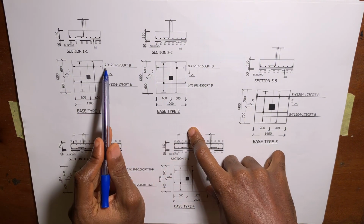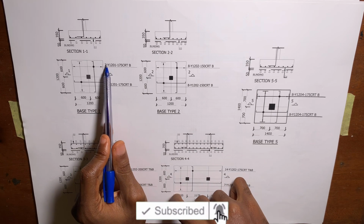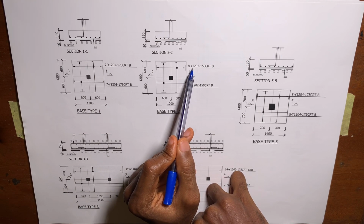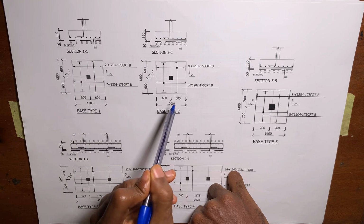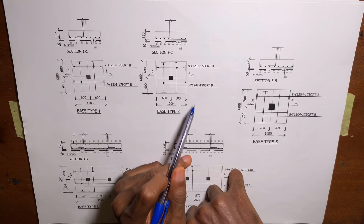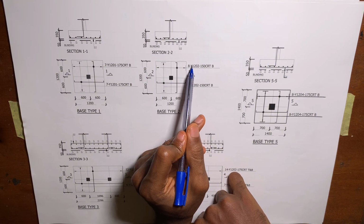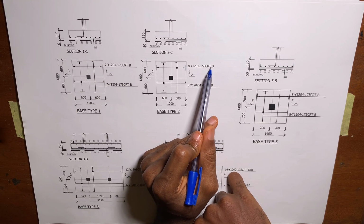In our reinforcement details for base type 1, they say that the vertical is 7Y12. But in our base type 2, they say that the vertical is 8Y12. So the Y12 reinforcement we're going to be having here will be 8 in number. That is why it is different from base type 1. That's why reading your drawing is very, very important. So for base type 2, the vertical bar, which is bar mark 2, is 8 in number, using Y12, and as you can see, 150 center to center, bottom bar.